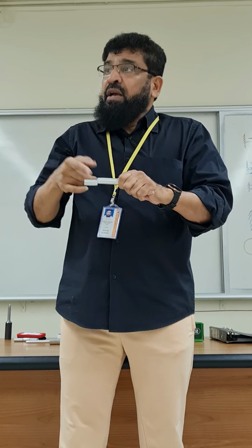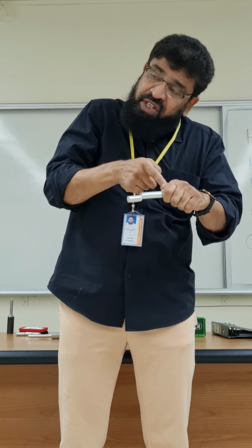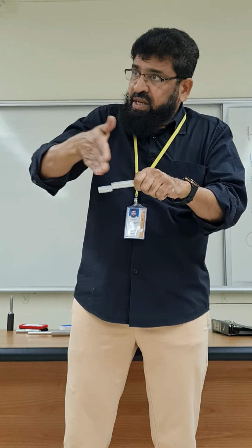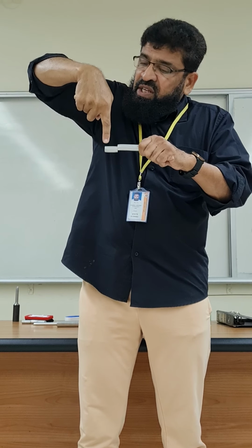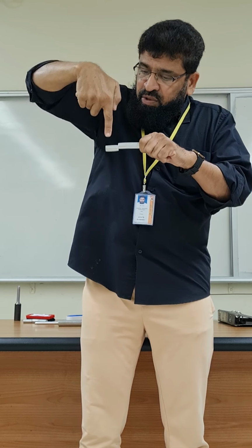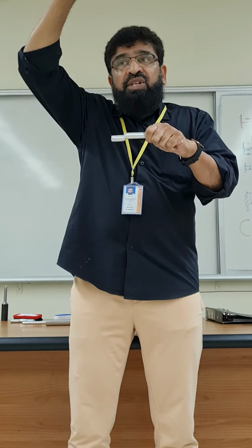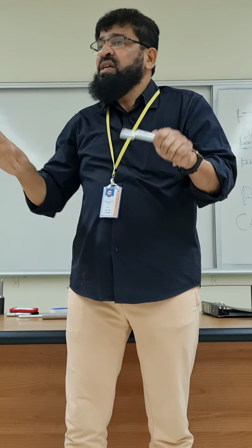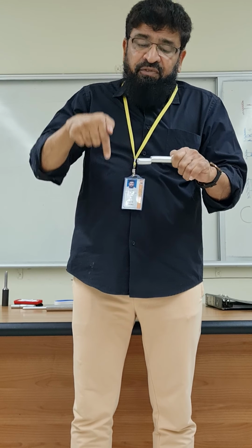Correct, Shabbat? It could have sheared here also, isn't it? It could have sheared at any of these points, anyway in this length. Okay? This force is called shear force. You got my point? I applied the force here. Because of this force of 100 newtons, shearing can happen at any point, constant. From this point to this point, the shearing force acting down is 100 newtons. Okay? Now shear force is acting like this.